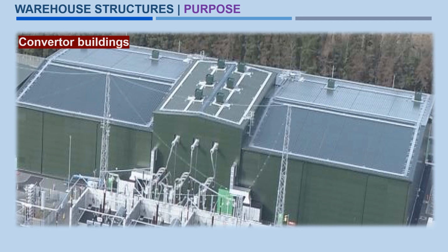Also this will have some converter equipment, so that needs to be taken into consideration, and the access to this building also has some restrictions, and a ventilation system is required for this. Sometimes during installation the vehicle movement inside the building also needs to be considered. Also an electrically operated crane needs to be considered for small maintenance and lifting of the equipment.